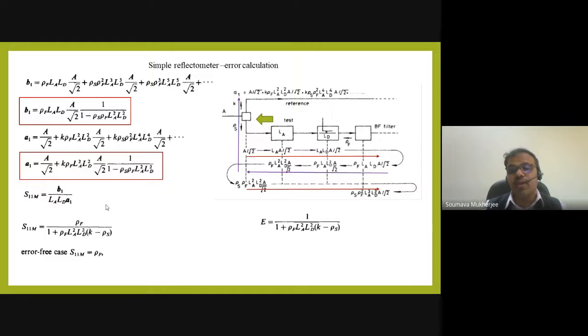Okay, so if you want to see the error, that error function looks like this. This is a very simplified form where we have not discussed that anything is reflected back at the attenuator part or the directional coupler part. If you added that up, then the function will be much more complex, right? Now, why is this attenuator used? Because we can see that there is multiple reflection into this path. That means once it is gone, again coming back, again gone, again coming back.